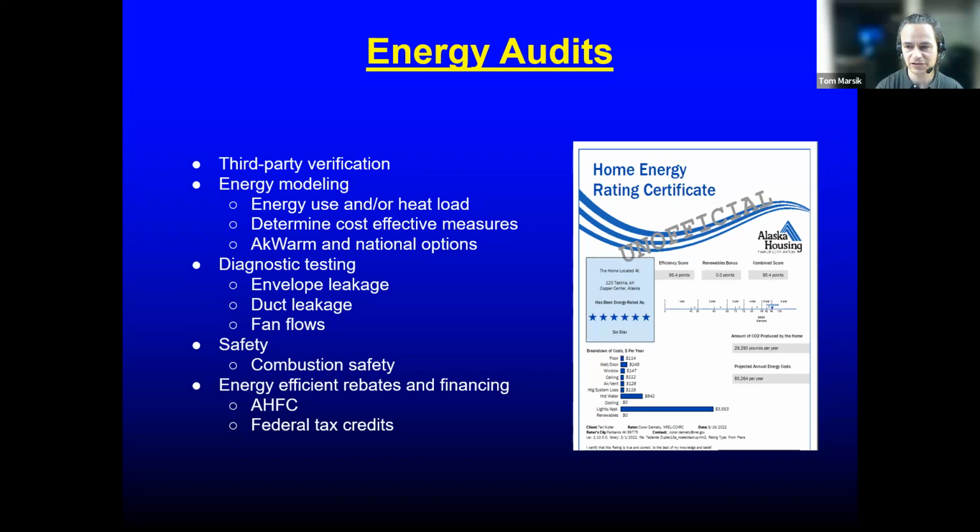In an energy audit, an energy rater comes to your home. The way it works is that the energy rater is going to look probably in the attic, if you have an attic, look in your crawl space, if you have a crawl space, look at your walls and windows and take some measurements and look at the materials, and also do some testing. Often it's a blower door test to test the airtightness of the building, sometimes some additional testing, and then they are going to process all that data and come up with an energy audit report for you.